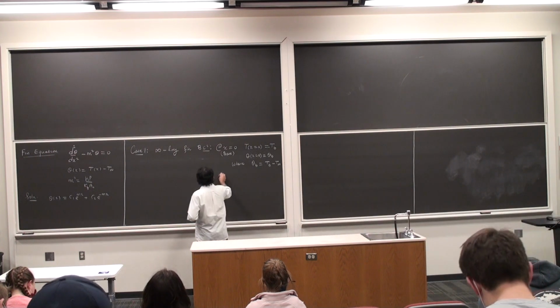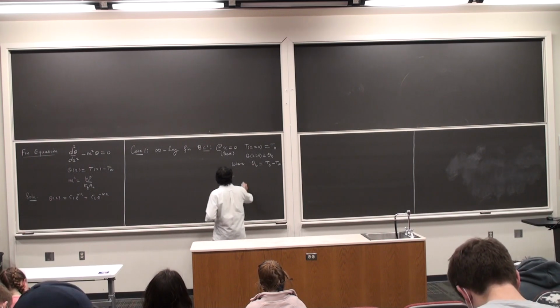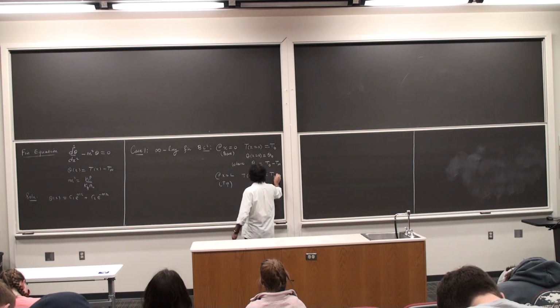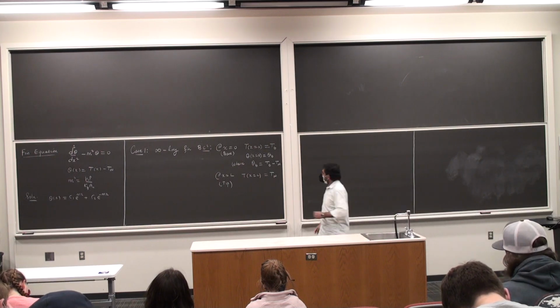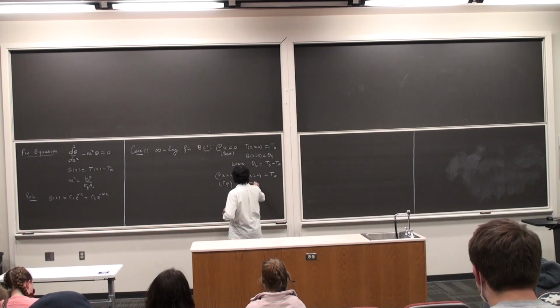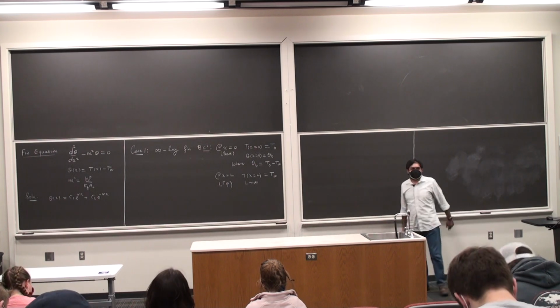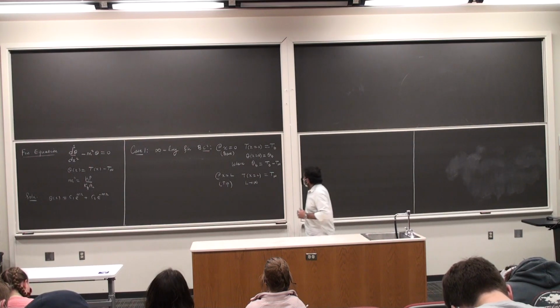And then the second boundary condition is at the tip of the fin, x equal to L, where L tends to infinity. Okay, this is an infinitely long fin. And we'll see that this is kind of an unnecessarily strict requirement. Does my fin have to be infinitely long? What the hell is infinite anyways?